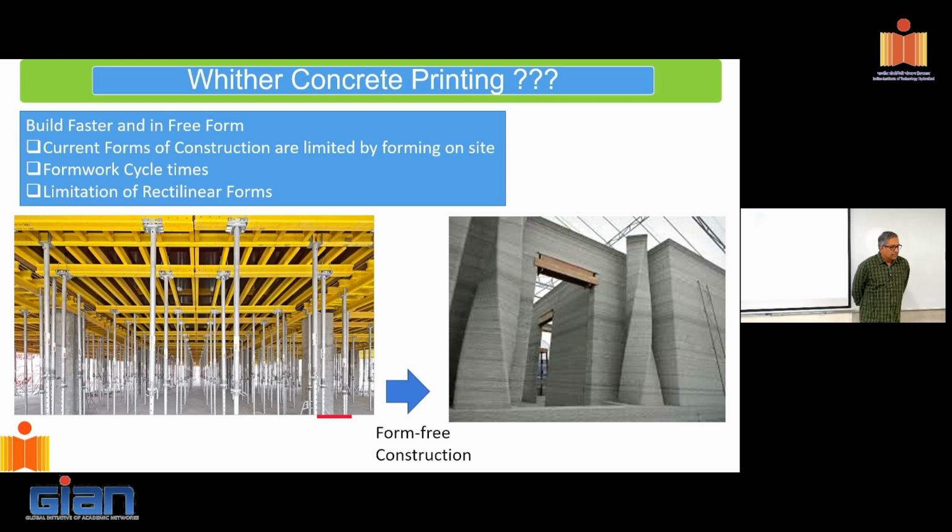Those of you who've done reinforced concrete design would know that by the time the span of the beam increases beyond 7 meters or 8 meters, it's like a dog chasing its own tail. How do we go around doing a rectangular beam design? Suppose I ask you to do a rectangular beam design with a certain loading. Say I increase the span to 8 meters or 10 meters. At some point, you'll realize that in order to meet the sectional capacity demand, you would have to make the cross section bigger. Now, when you make the cross section bigger, it only brings in more weight. So basically it contributes more to the demand.